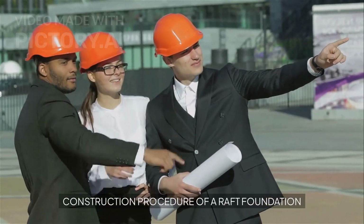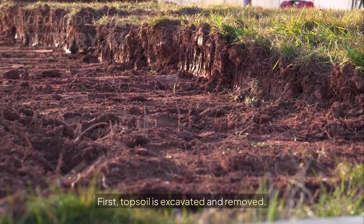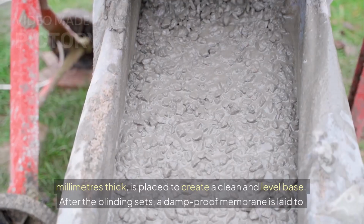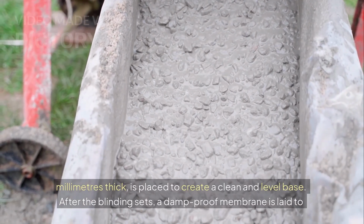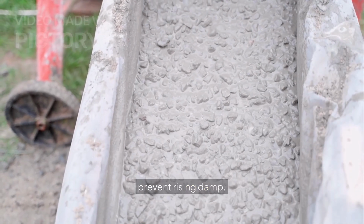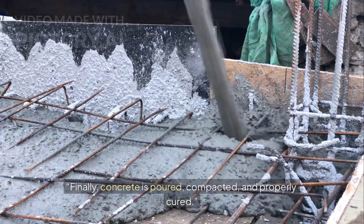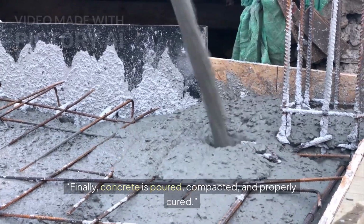Construction procedure of a raft foundation. First, topsoil is excavated and removed. Next, a blinding concrete layer, usually 50 to 75 mm thick, is placed to create a clean and level base. After the blinding sets, a damp-proof membrane is laid to prevent rising damp. Reinforcement is then fixed according to the structural design. Finally, concrete is poured, compacted, and properly cured.